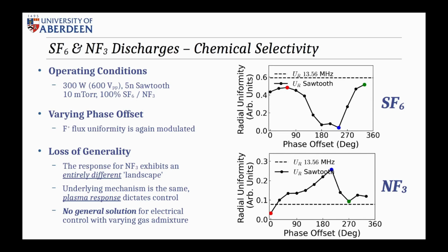That changes with the energies, so that changes with the biasing, that changes with the temperature of the wafer, if you've got a cryogenic wafer or a heated table or anything. A million different parameters can change. And I've kept as much as I possibly can the same, and I've trimmed these two reaction mechanisms down to be only about 150 reactions each to make them nice and simple to compare. And yet, even under these idealized perfect conditions, where we're comparing as like for like as we possibly can with two fluorinating gases, we end up with 180-degree out-of-phase control results. The best case for SF6 is the worst case for NF3 and vice versa almost, right?